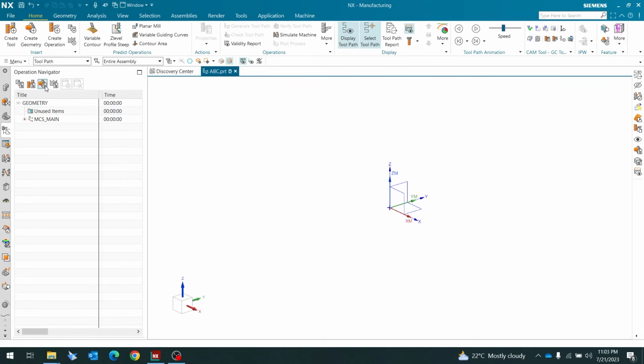The third one is geometric view. It is a very important view. Whenever you are starting any project in a CAM, you have to work in geometry view while generating specifically operations, where you can get this MCS, Workpiece and other controls. So from scratch, whenever you are working, you have to use this particular geometric view.